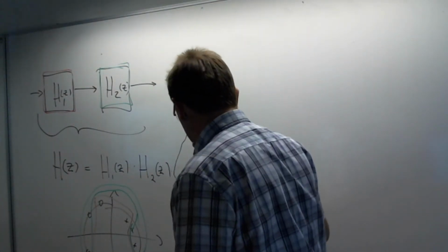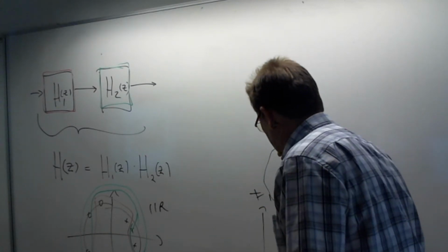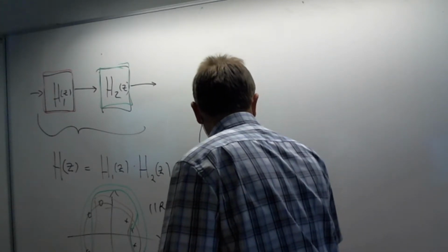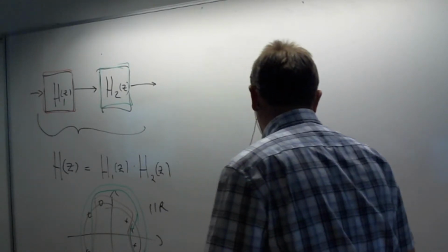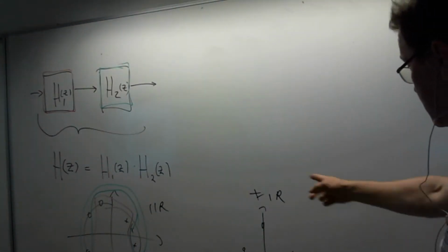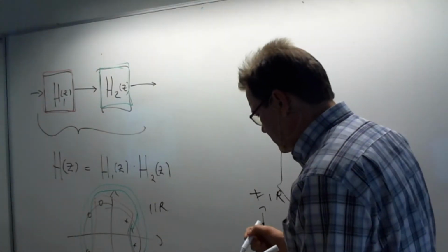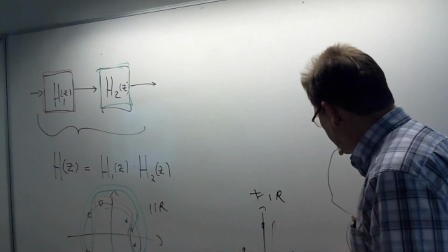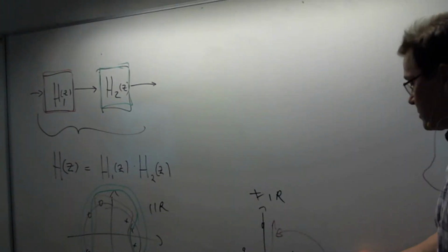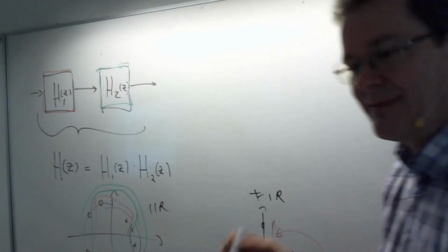Okay, so that would be IIR. Then if we have a FIR system with the impulse response symmetric like that, and these will go very small here. You have seen these before, for example in the FIR exercise, where you needed to plot the impulse response. But anyway, the magnitude of this one could be totally different in order than that one, meaning that when you're doing the calculations, this could actually be less than the calculation accuracy, but it still affects the system behavior.